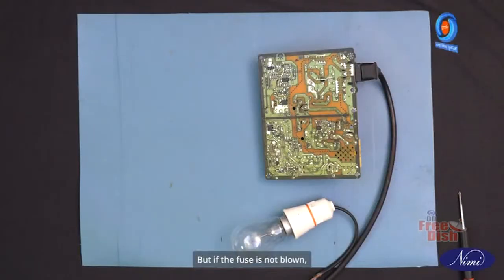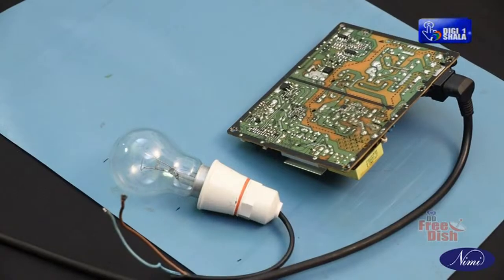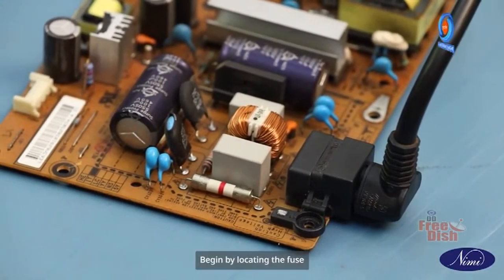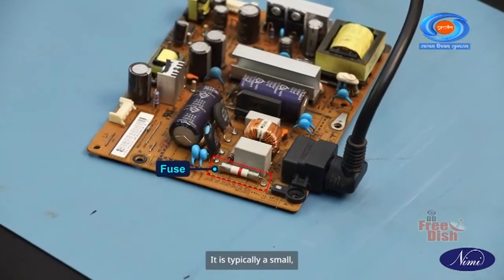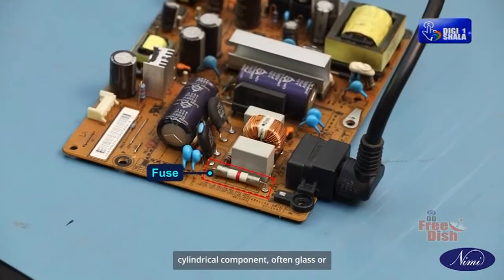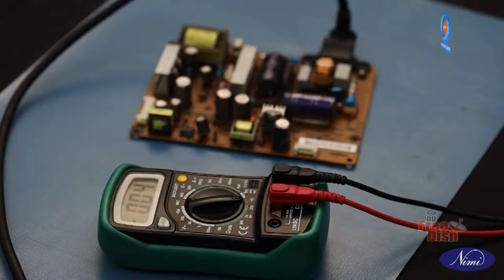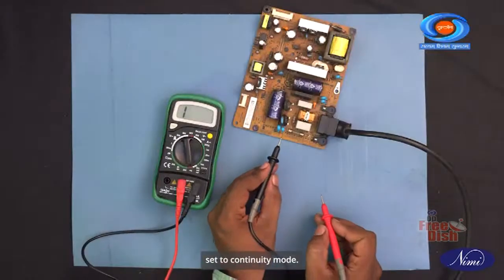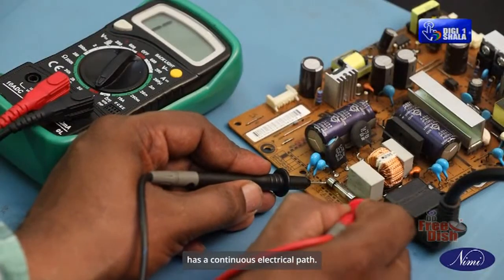But if the fuse is not blown, the capacitor charges up and then the lamp lights up as the capacitor discharges. Next, we will inspect the fuse. Begin by locating the fuse on the power supply board. It is typically a small cylindrical component, often glass or ceramic, with metal caps on either end. To test the fuse, we will use a multimeter set to continuity mode. This setting helps determine if the fuse has a continuous electrical path.